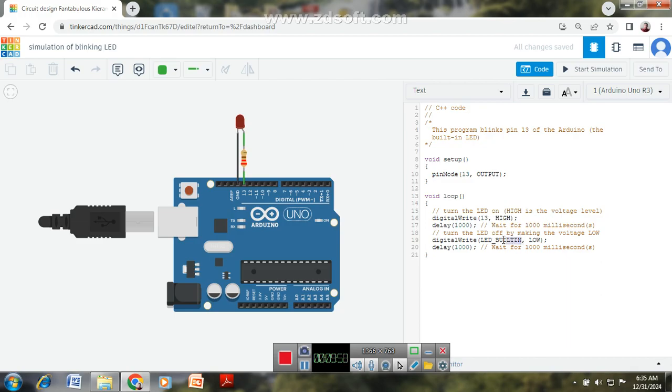Afterwards, with the help of pin 13, this entire program is going to be used. You can also connect this in different digital pins. Whichever pin you are going to connect, you have to give the correct pin connection here, then only it will function. Your void setup is used for pin mode connection, either input or output. Here in this program you are using output connections only.